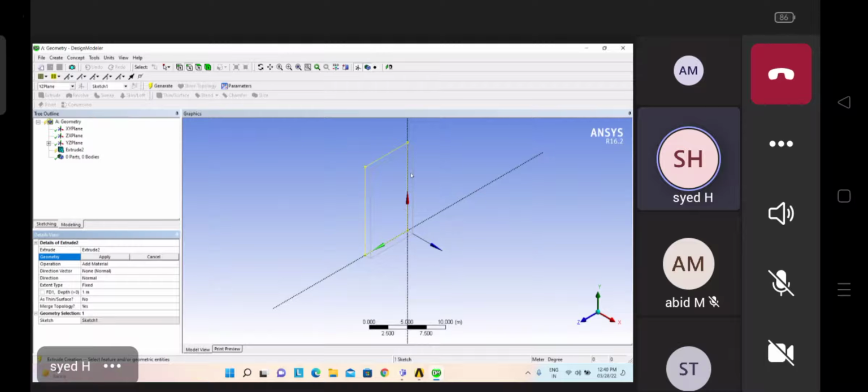If you have multiple bodies, then in that case you have to select this sketch for performing the extrude operation. Now see here, after creating extrude, the first thing it will do is ask you to select the geometry. The geometry is already selected there. And remember one thing, whenever you are selecting, if you want to select the complete sketch, always select from this place. From here onwards, you have to select. Otherwise, if you select from here, it will select only a single line like that.